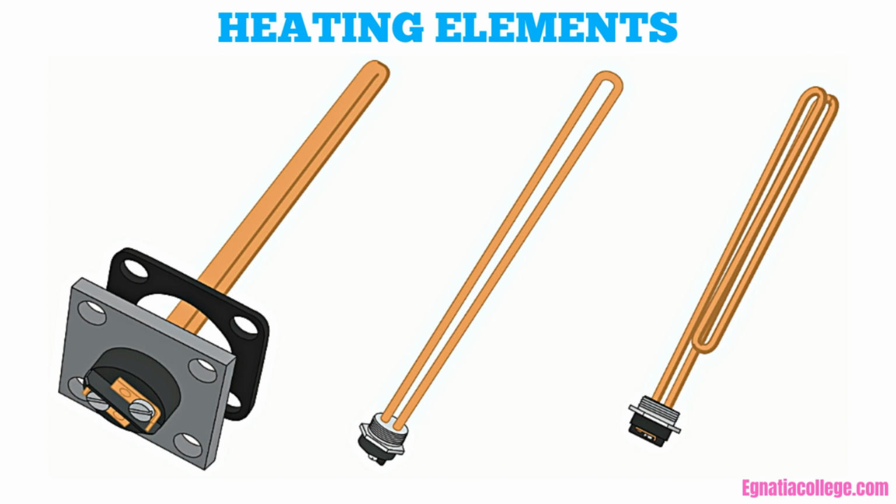These elements will produce rated wattage output at rated voltage. When operated at less than rated voltage, the wattage output will be reduced. The effective voltage variation is discussed later in this unit. Most heating elements will burn out if operated at voltages 5% higher than that for which they are rated. To reduce the element burnout situation, some manufacturers will supply water heaters with heating elements that are actually rated for 250 volts, but will mark the water heater 240 volts with its corresponding wattage at 240 volts. This allows a cushion should higher than normal voltages be experienced.